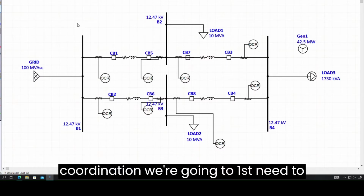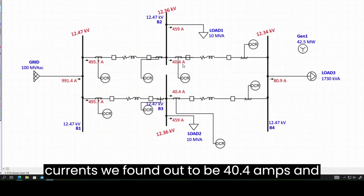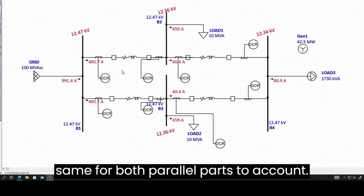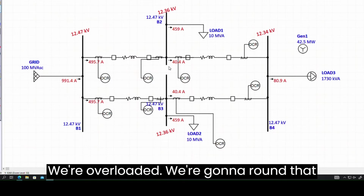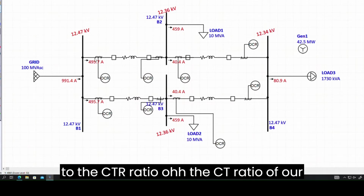So for the coordination, we're going to first need to figure out the line currents. The line currents we found to be 40.4 amps and 495.7 amps, and it's going to be the same for both parallel paths. To account for overload, we're going to round that off. This will be 50 and this will be 500. Those values are going to be applied to the CT ratio of our relay.